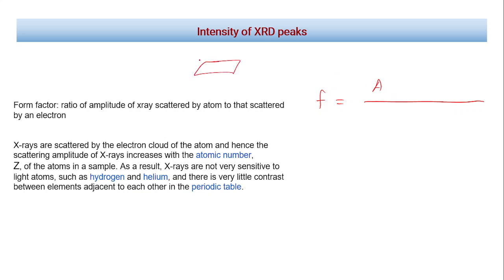So I told you, right, sometimes we talk that the X-ray is incident on all the atoms, coming in on their atomic arrangement on the plane, and they are diffracted from this. Sometimes we also say the X-ray is reflected, because then we consider not the atoms but the plane on which these atoms lie. So it's like reflection from a mirror. That's why we use the word reflection.